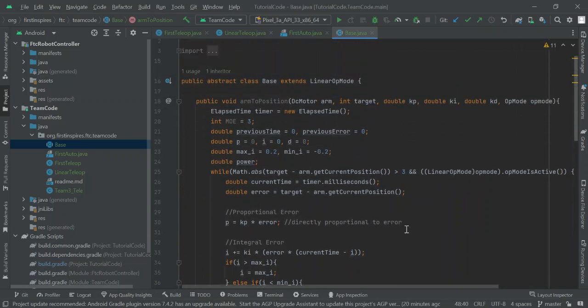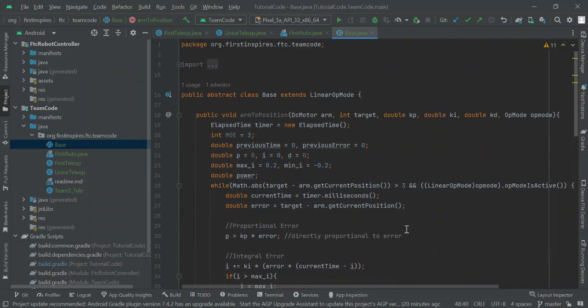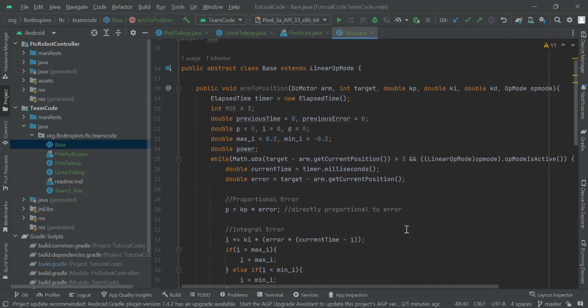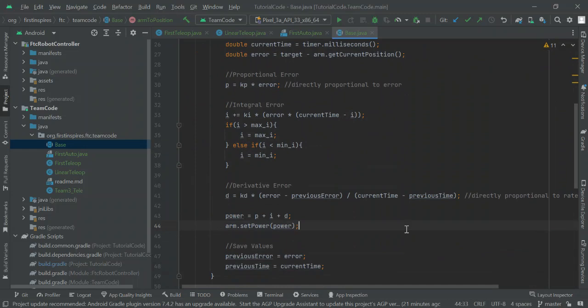And this is the beginning base of the applications of PID in FTC. The actual scope of usage for a PID loop in FTC is huge, and it's vital to learn for effective programming. So in the next videos, we're going to dive into something called a feed forward, which is used to compensate the effect of gravity on your arm or slide system. So we're going to learn how to run a PIDF loop and also how to use PIDs in robot movement. And again, from now on, I'm going to be only using the P and D parts of the loop, as there is really no use for I in FTC.